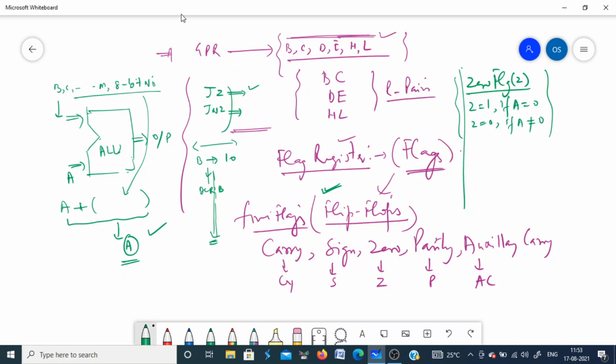For that we can use the zero flag. Every time you decrement it, the register goes from 10 to 9. The next time you decrement it, it goes from 9 to 8, and so on. Then you have to see whether it is 0 or not.